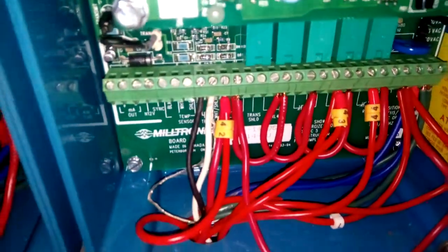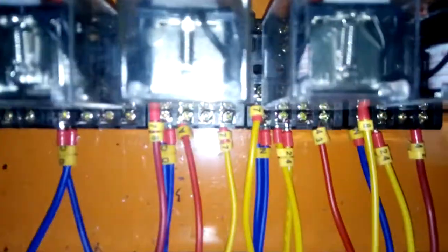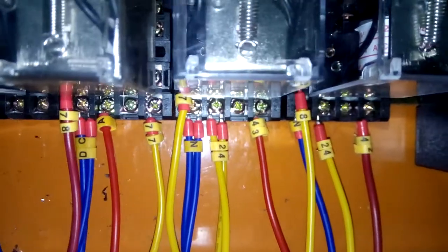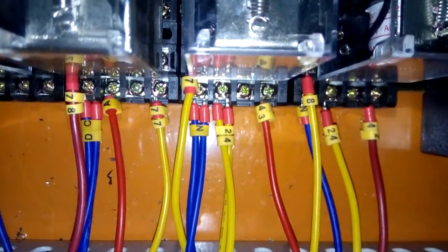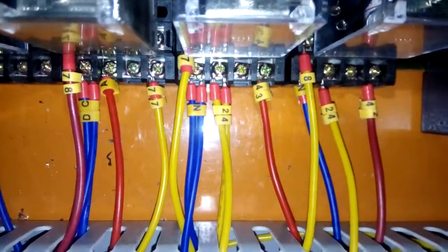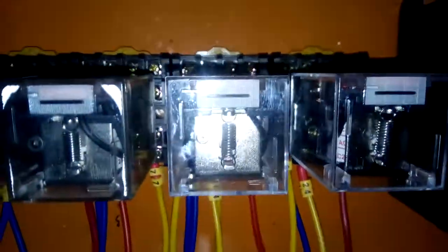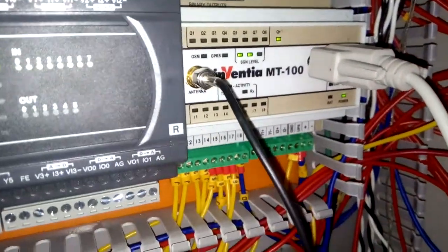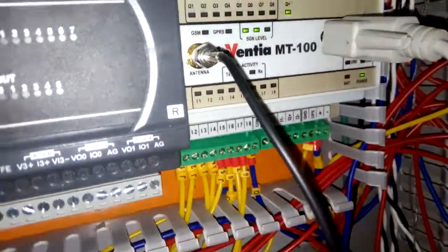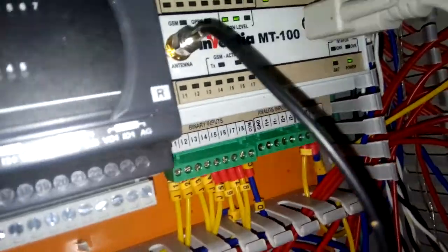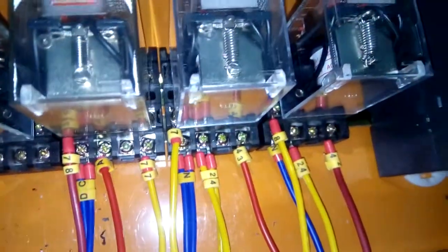at the pumping station. So those two signals are routed to these two relays, 43 there and 42 on this other side. And when they come to the relays, then they join the telemetry module in the inputs. That's 8 and 7, as you can see, 8 and 7.